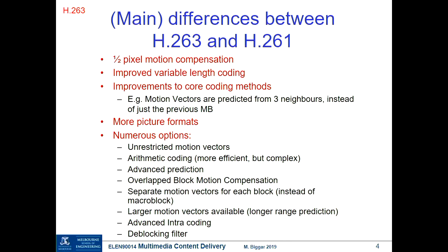I think when we talk about this, sorry. Okay, so when motion vectors are coded, I don't think I talked about this before, but you would expect a fair bit of correlation between the motion vectors in adjacent blocks. So if a large part of a picture is an object that's all moving in one direction, more or less, then the motion vectors will be correlated, as will the pixels.